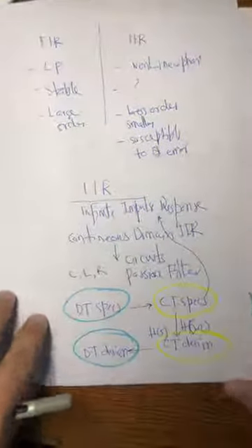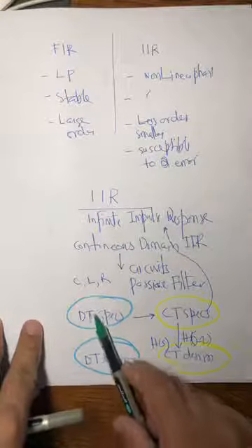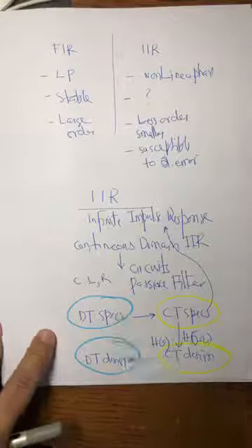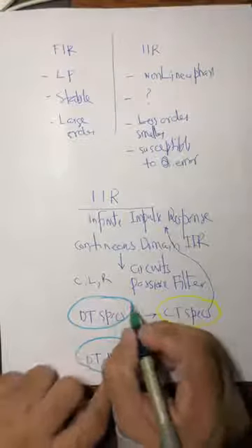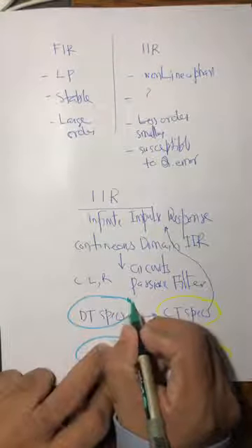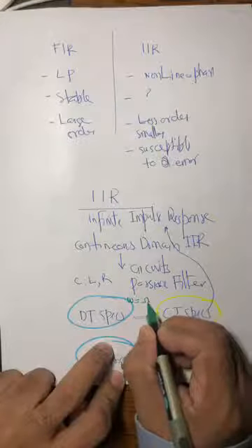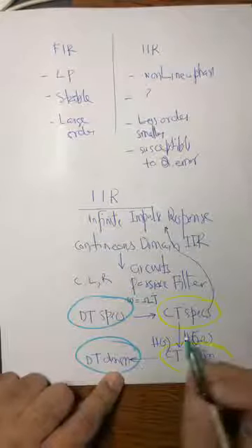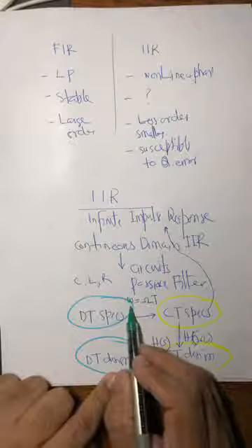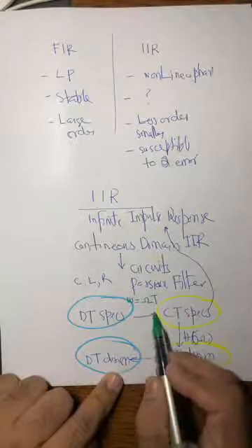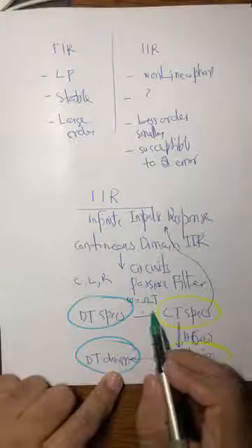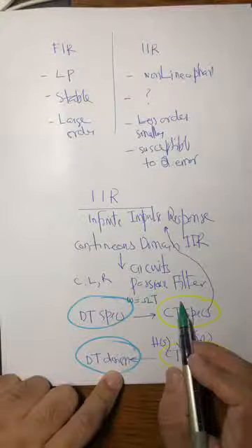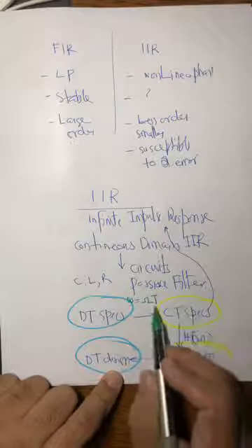What they do is they have these specifications for a discrete time filter, so they convert it. And once they are converting, usually the simplest way of conversion is you take small omega is equal to capital omega into T. Okay, so you take small omega is equal to capital omega into T. So the small omega frequency is converted using capital T, though you are not actually converting a discrete signal into a continuous one, only mathematically. So you assume any T.